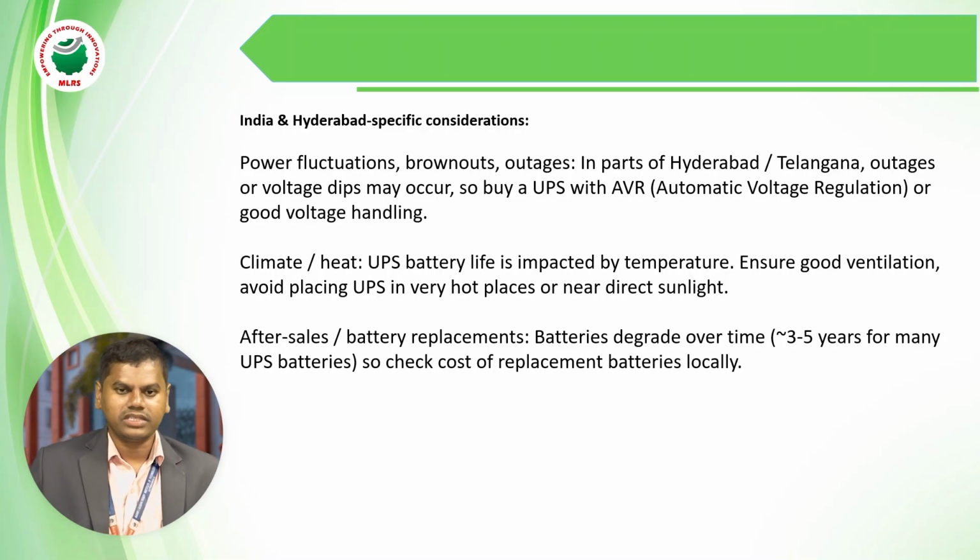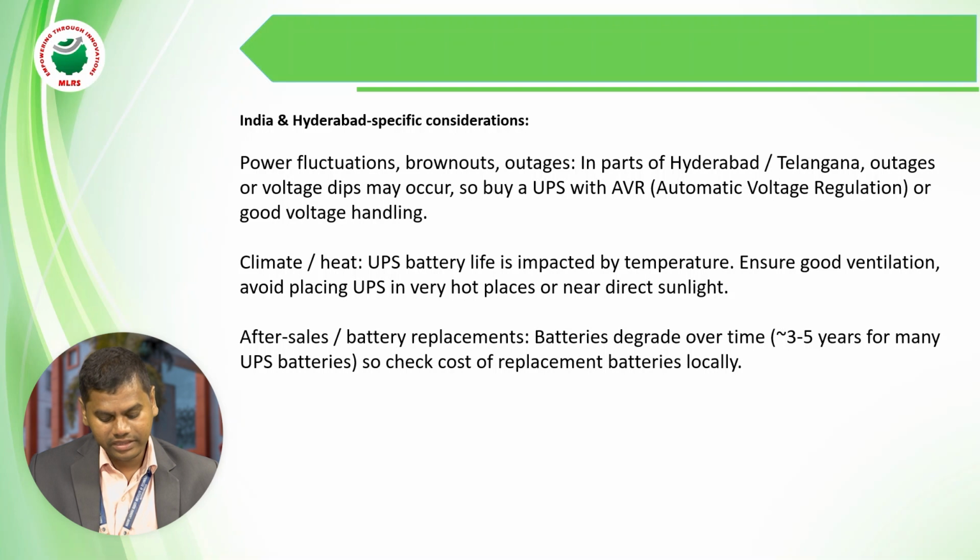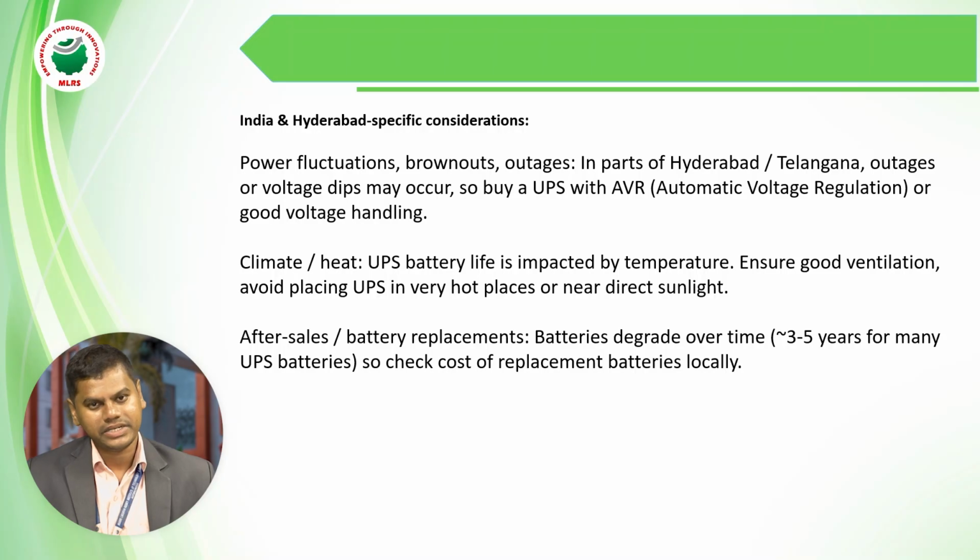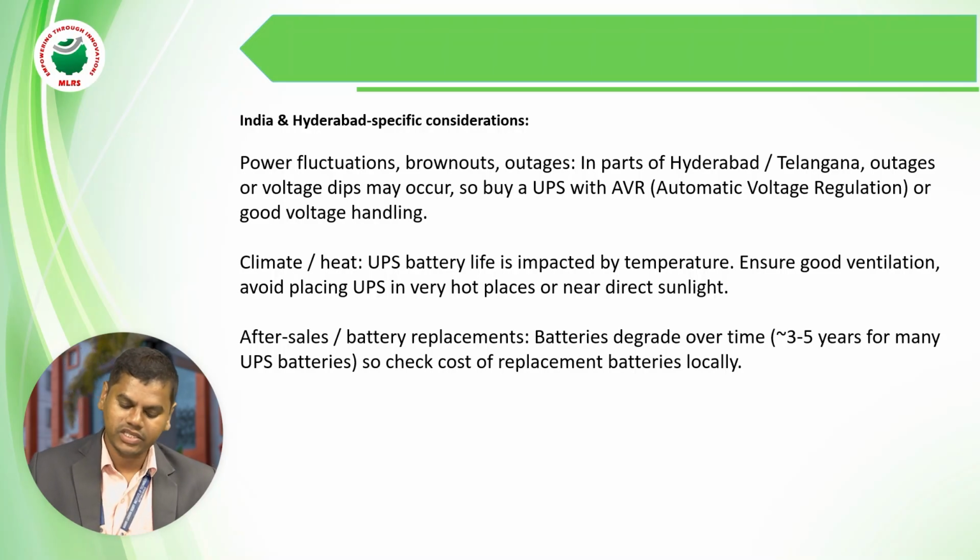So next, suppose climate. So how is the climate? Here the climate is nothing but heat. So UPS battery life is impacted by temperature. So ensure good ventilation and avoid placing UPS in very hot places or near direct sunlight. And next, after sales and battery replacements.